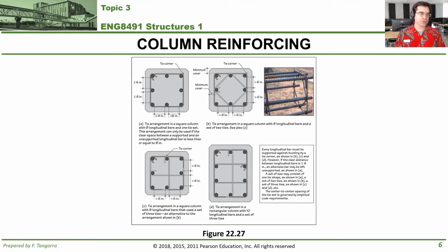Concrete reinforcing can be set out in very different ways, but for the most part it follows the same pattern. You can see here a section cut out, a slice cut out of the concrete column. You have a tie with longitudinal rebar placed at the corners and halfway between the corner rebars. This is the setup that you'll typically see if the rebar is spaced no more than 6 inches apart. So that's about 150 millimeters.